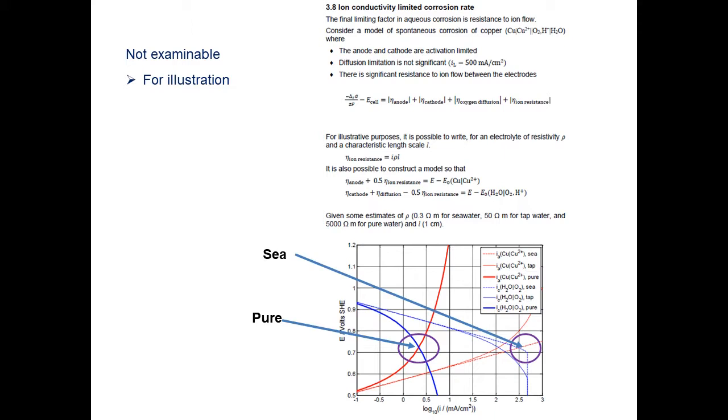When we look for the solutions to this system when we have pure water, which is much slower corrosion than we see in seawater. And this is just because of different ion conductivities. So we have seawater being much more corrosive just because the roughly 0.6 molar sodium chloride solution is so much more conductive, hence faster corrosion.